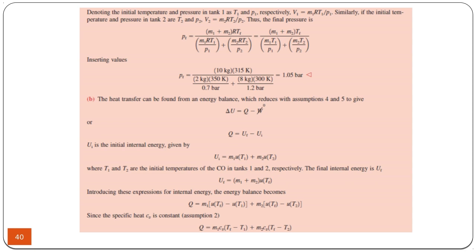This is important. So when there is no change in volume, as you can see, the volume does not change. The total volume is the same. So we should say that the work done here is zero. So it means that during this mixing, the heat exchange between the two is U final minus U initial.